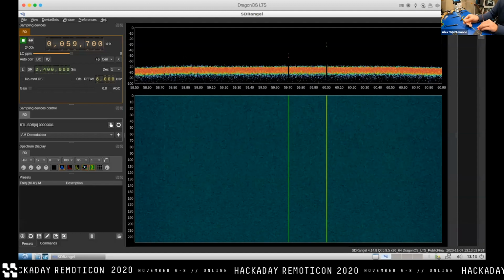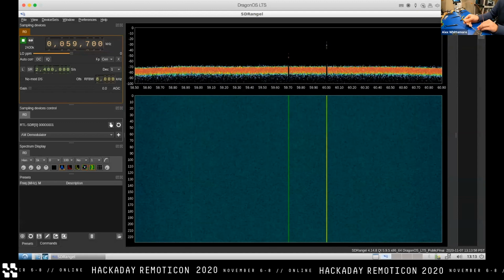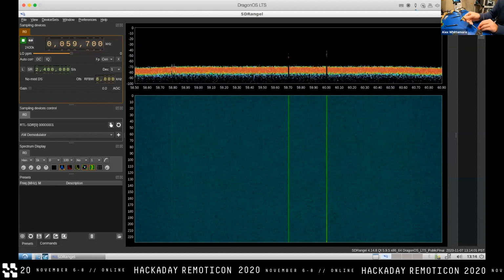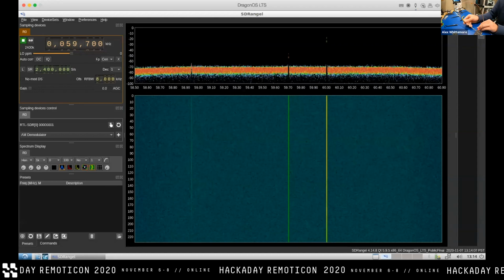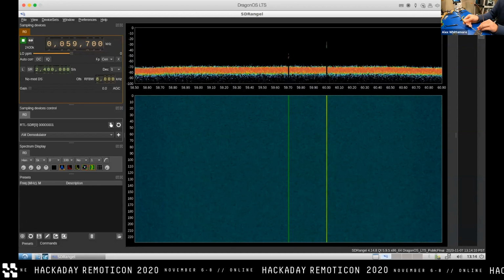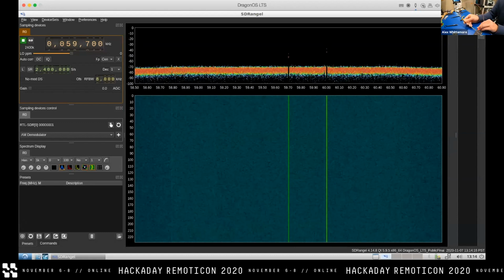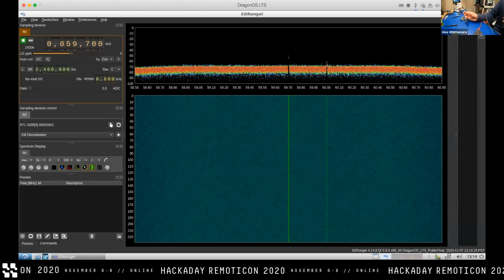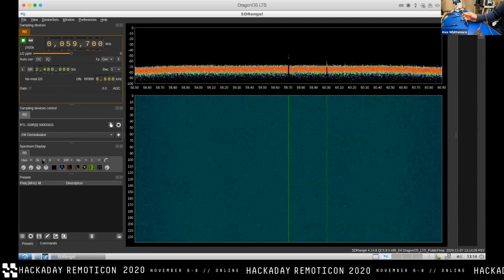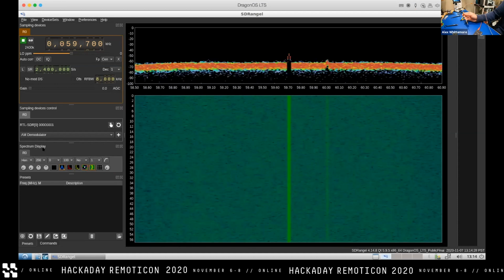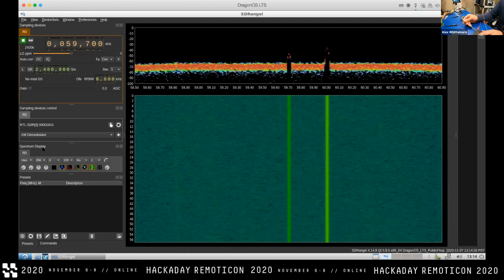For any particular case, you basically have to feel around for the combination of settings and tools that work best in that case. What we can see as we get close to this little capacitor that's right here, that capacitor certainly has some serious current going into it at that 60 megahertz mark. And obviously, if I pull away, that line goes kind of dim. If I come in really close, that line is nice and bright. Like, we can really see something going on there. And basically pinpoint which pin it is by figuring out where it's the brightest, where we're moving our wand. Okay. Make that bin even a little bit wider. Okay, yeah. That's nice.